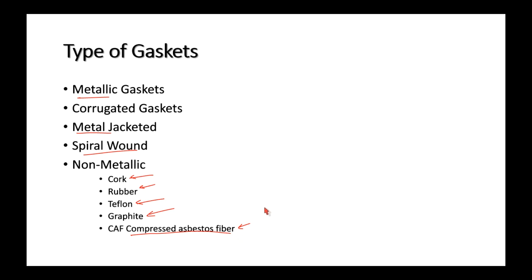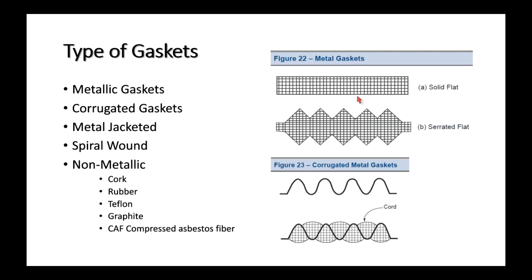So if it's ever your job to remove gaskets in a plant, somebody says, yeah, I need you to, we got this pipe apart, or we got this pump housing apart, I need you to clean up the gaskets. Find out what the gasket material is first before you clean it, because if it contains asbestos, you have to be extremely careful. I can tell you a story, but I won't, and it involves me and it involves asbestos. It involves not knowing, so not good.